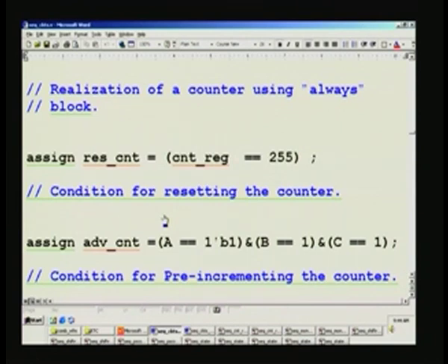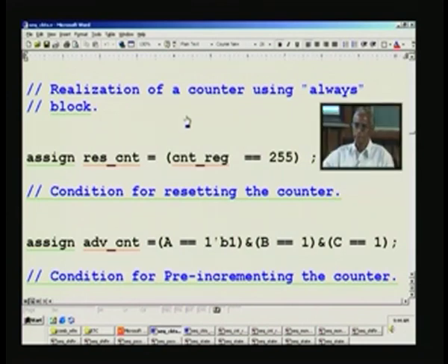Because at this stage I wouldn't have decided the device, isn't it? Yeah, we haven't. So 40 megahertz or 50 megahertz is probably only an assumption based upon our prior experience. I have just put some 50 megahertz, 20 nanosecond is the time period. So that works out to be 1000 by 20. Always divide 1000 by 20, you will straight away get it in megahertz, right? So that works out to be 50. So 50 megahertz is a typical value on an FPGA, and that is the reason why I stuck onto that.